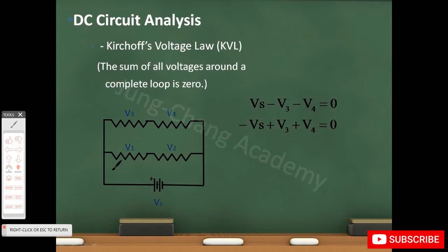In this case, if we assume the current flows from the left to the right, like this, because we know that current flows from a higher potential to a lower potential, we will have plus here, negative here, plus here, and minus here. So now we use Kirchhoff voltage law on the outermost loop, this one here, in the